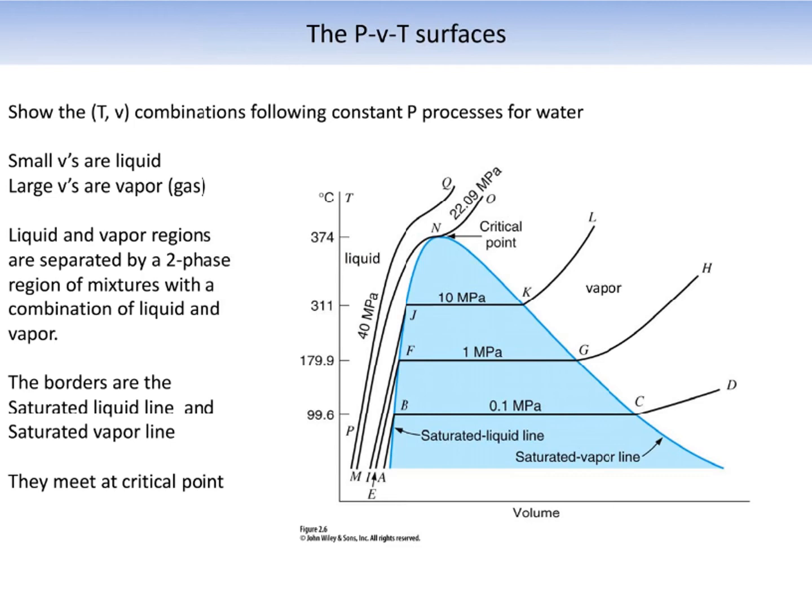For this curve, we have assumed that the initial temperature is room temperature, and the pressure during the complete experiment is atmospheric pressure, 101 kilopascal nearly, so 0.1 megapascal. This 0.1 megapascal remains the same for the entire length of the experiment. Only the temperature and volume change.